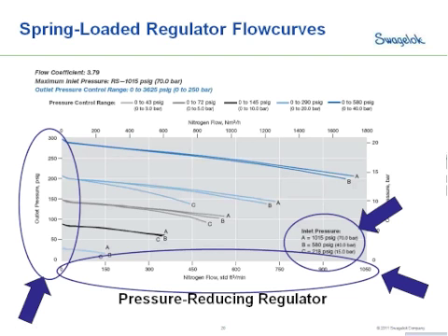And the last thing we need to know is our target flow rate. And our target flow rate is probably going to be a range. It's very unusual to have a single flow through a regulator constantly. They typically have a range that they're going to operate within. So with these three pieces of information, we can find and select a curve that will meet our application, and from there will lead us to the proper regulator for our system.